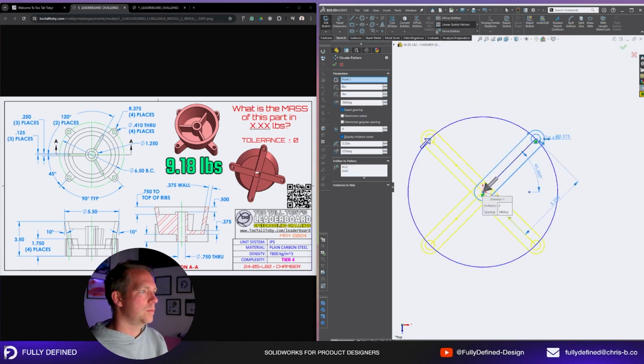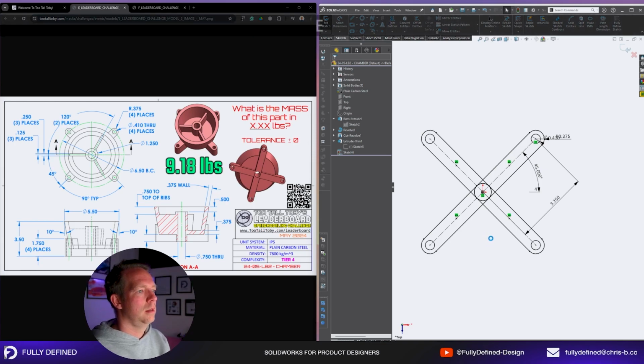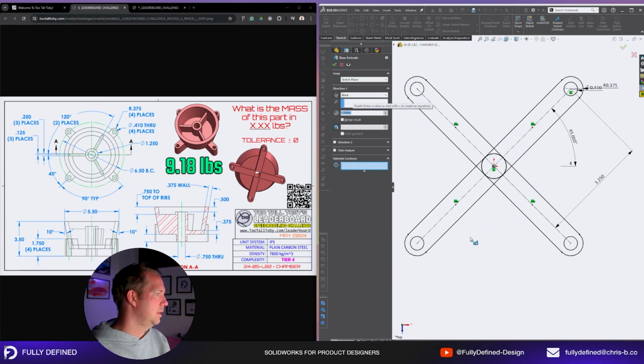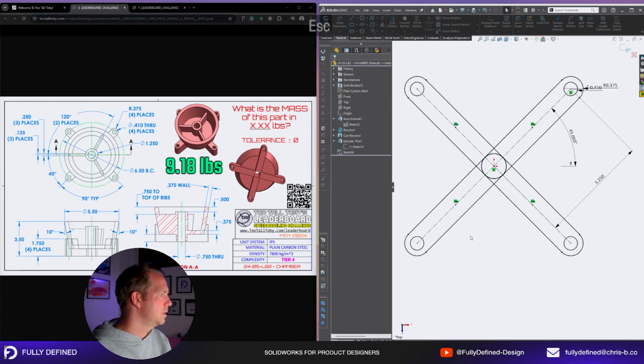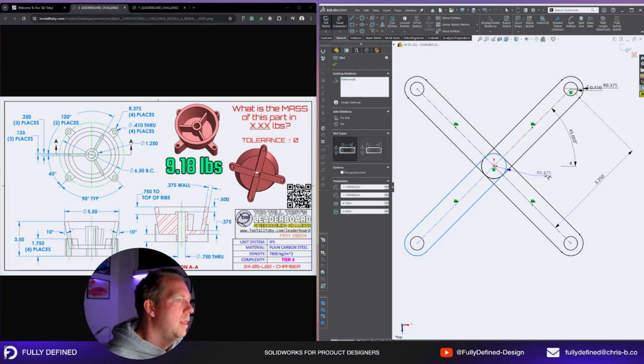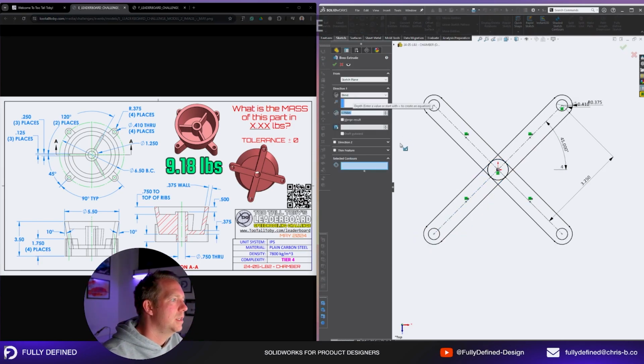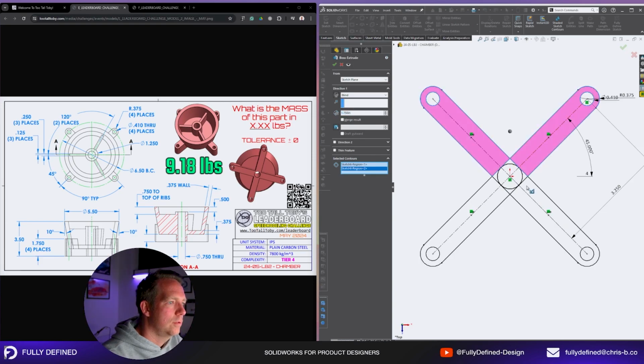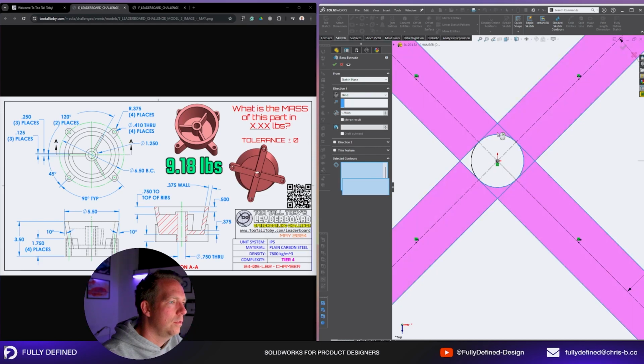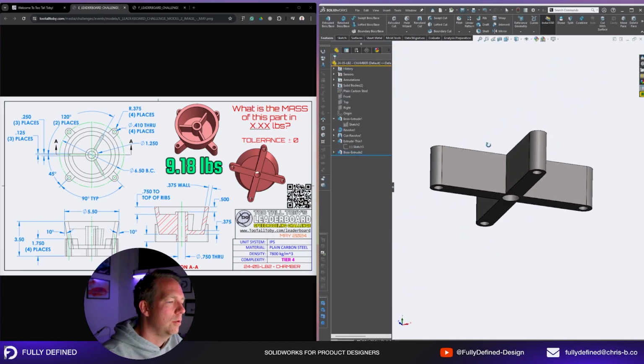I feel like that's going to cause problems. Well, maybe you can see that circle in the middle. That actually might work really well because that circle becomes our 0.375, our 0.75 through hole. That could be really handy. So we're going to extrude. We're going to do 4 selections. This is the part I don't like. We have to do 8 selections, but we already get a hole.